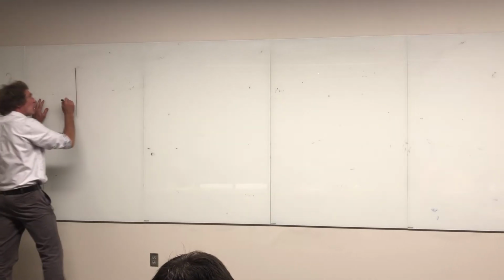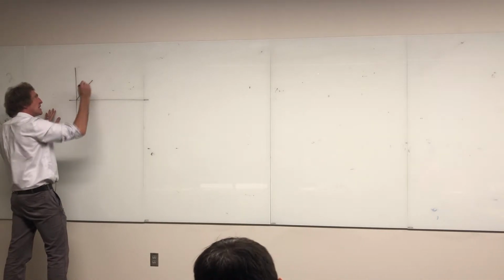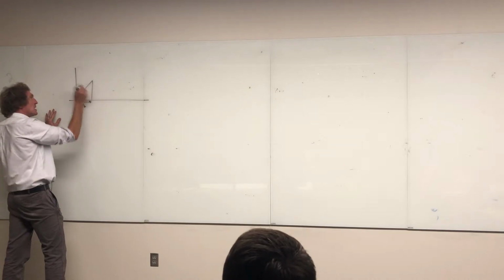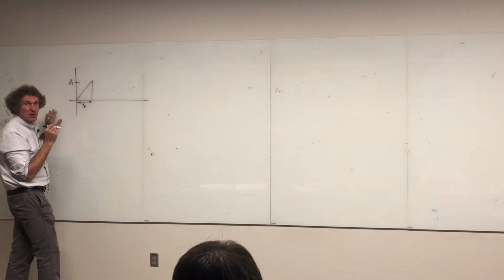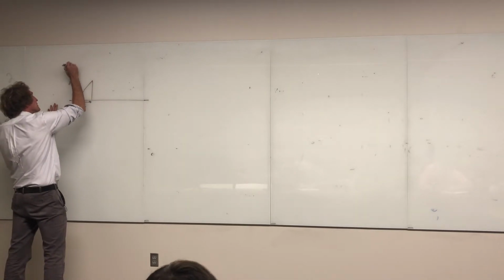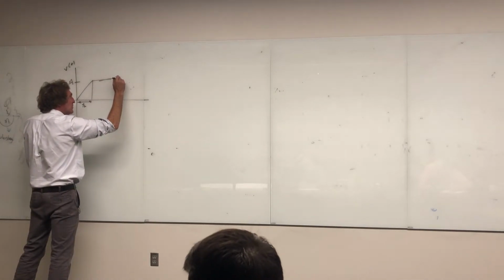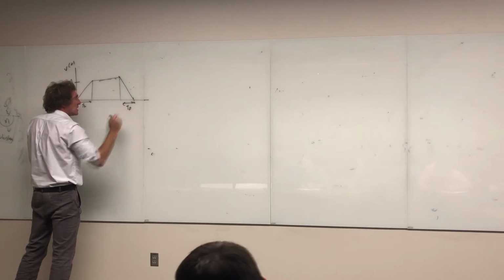Normally when we talk about waveforms that are digital waveforms, they repeat themselves. They have a certain rise time. This is called tau rise. They go to a certain amplitude A. This is a standard clocking pulse. This is where all the EMC problems come from. And this is going to be a voltage, V of t, not a current. Comes over, stays flat, and then it will fall off down to here. This is called the fall time.